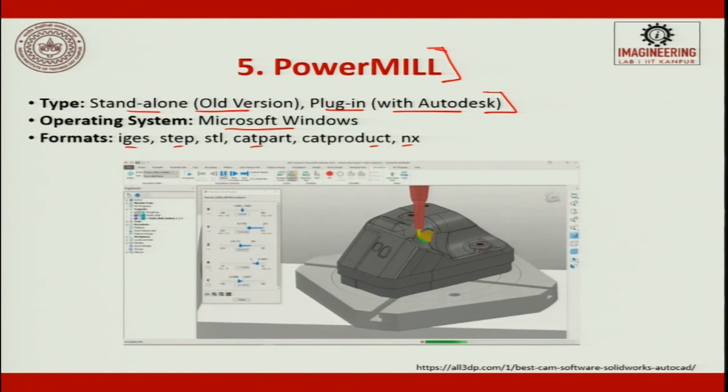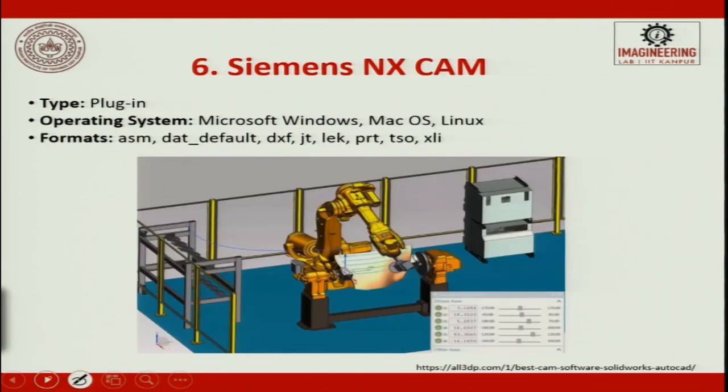One of the unignorable features of PowerMill is that this CAM software natively imports third party file formats like Siemens NX CAM or CATIA. It preserves the association with these software as well. This means that you can change your design in one of these programs and PowerMill will then update the tool paths accordingly.